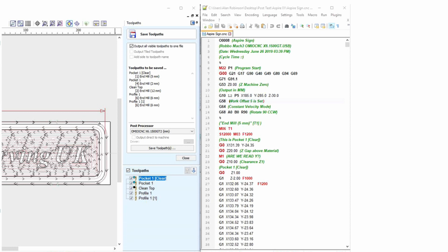G10 tool offset and work offset tables. Line 12, this is set from within the post processor depending which work offset you selected. G54 to G59 and G59 P1-254 work offsets. To select work offset number 1, program G54, and similarly for the first 6 offsets. The system number G-code pairs are 1 G54, 2 G55, 3 G56, 4 G57, 5 G58, 6 G59.